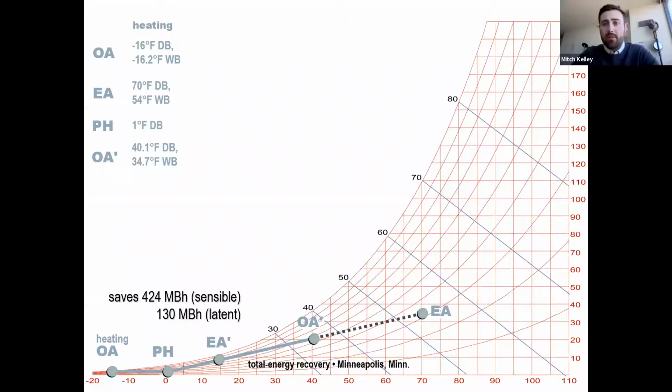And truly energy modeling is going to be required, because your building envelope is going to come into play when you're calculating that out. What's the exact balance point in terms of percent of OA? It's really building to building, case to case.